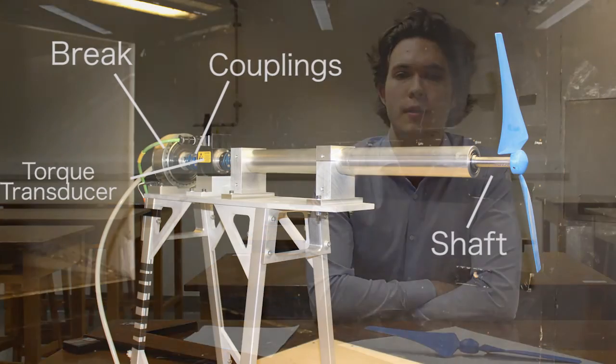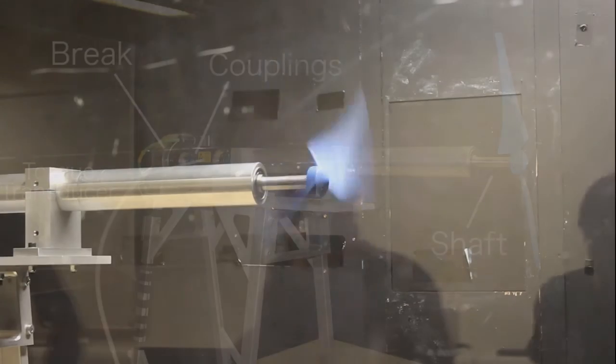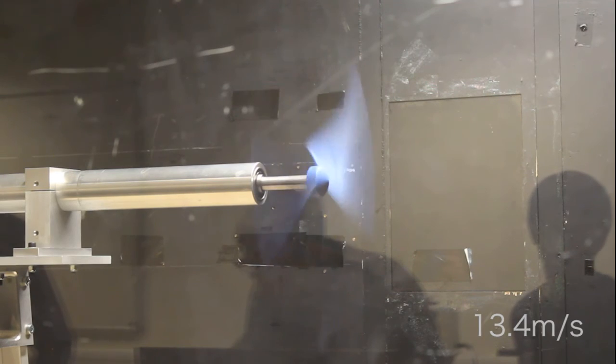The turbine was tested in the Donald Campbell wind tunnel using a setup with a grease shaft, flexible couplings and a data recorder. The turbine properly self-started at a wind speed of 13.4 meters per second, and following that was able to run at 12, 10 and 8 meters per second.